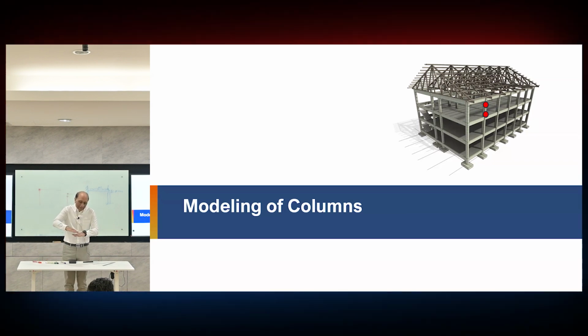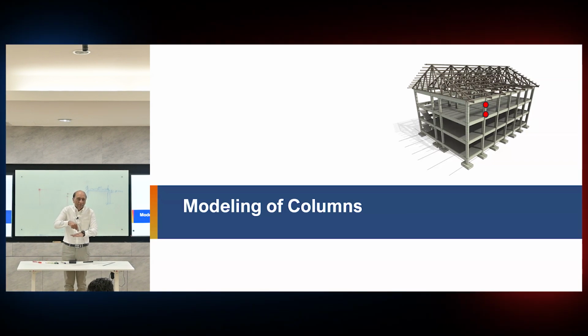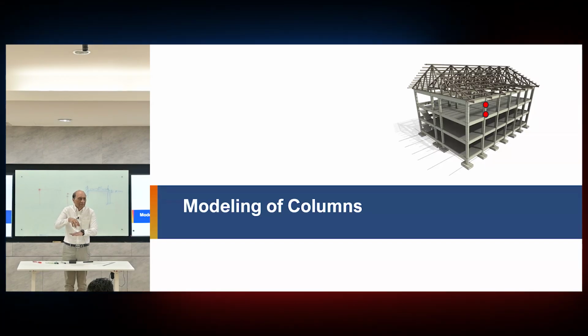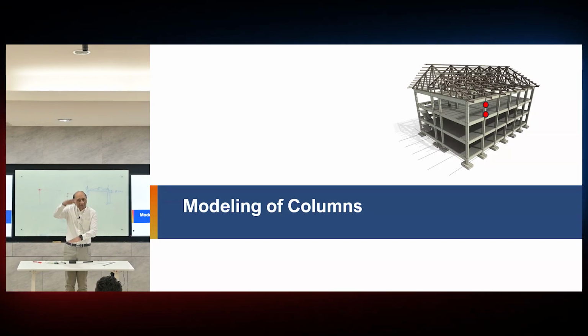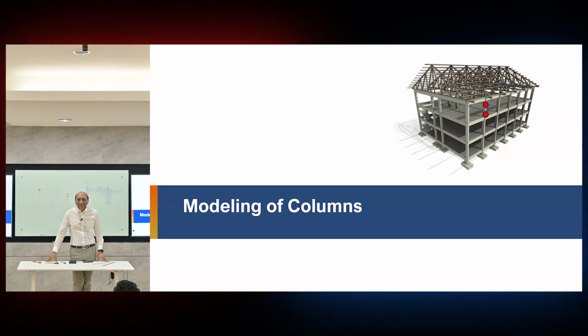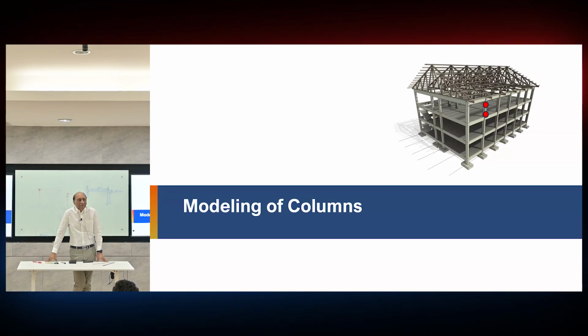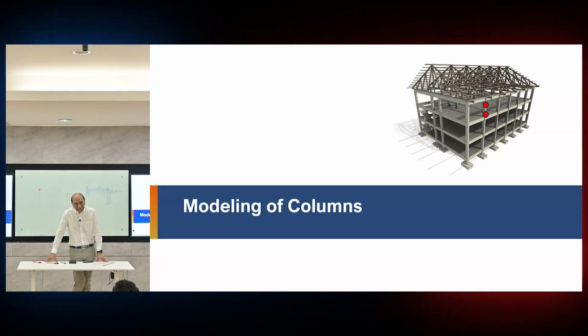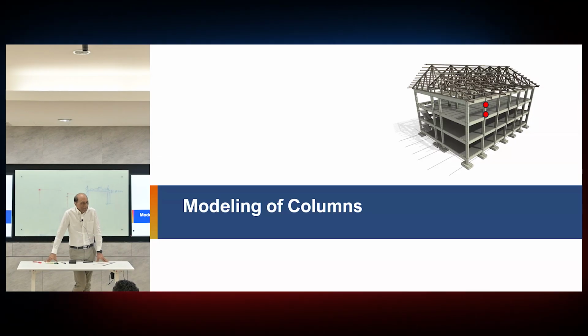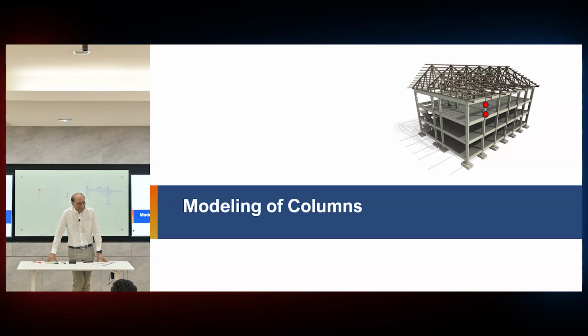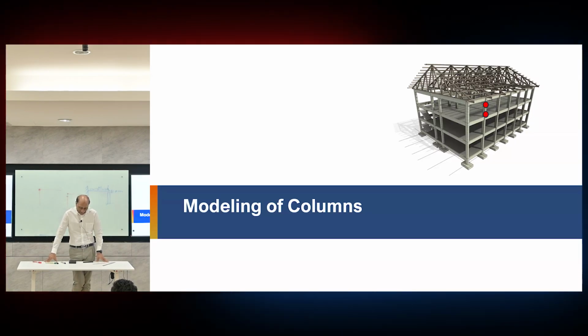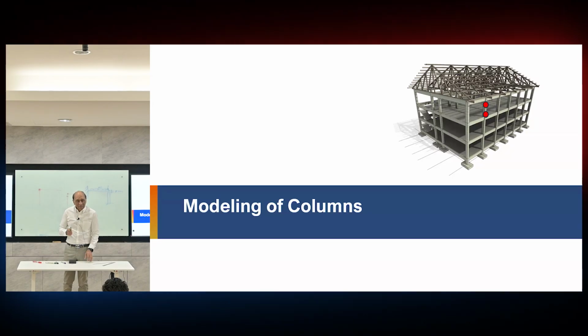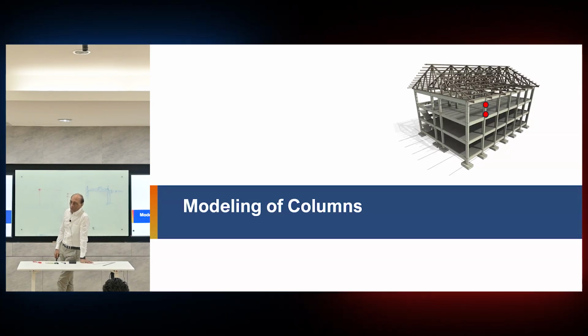We tell the program the details of the column, where is the rebar, where is the material. We define the section, and then it generates the PMM hinge as required for a particular load combination at that time. So it's a live development of the hinge and use that one. So that's why it's not practical to use the simple hinges. We need fiber.